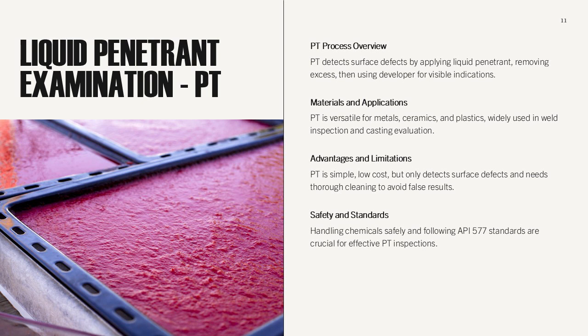Advantages include simplicity and low cost, but PT is limited to surface defects and requires thorough cleaning to avoid false indications. Safety considerations involve handling chemicals and ensuring proper disposal. PT is commonly used for weld inspection, casting evaluation, and detecting fatigue cracks in components.